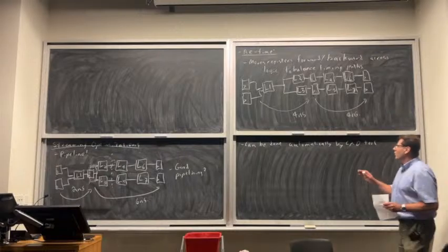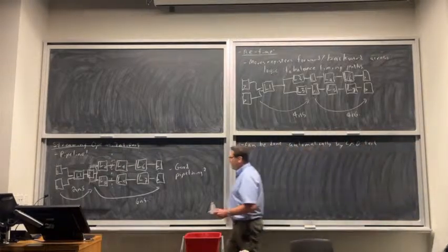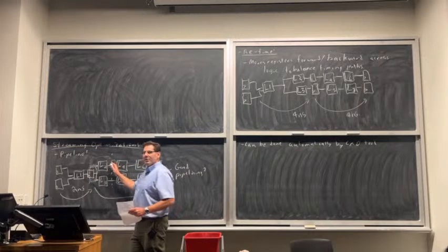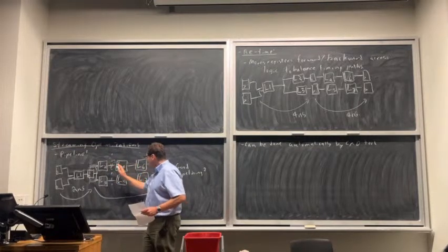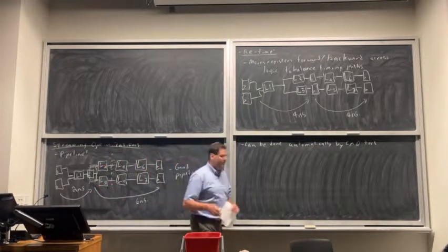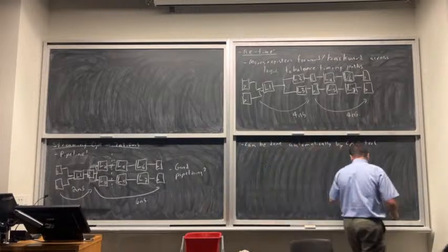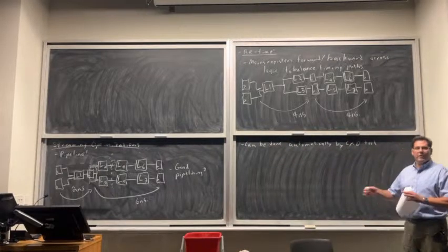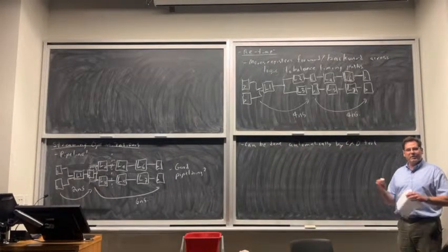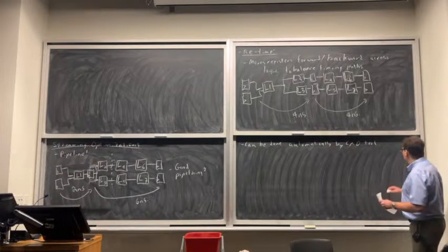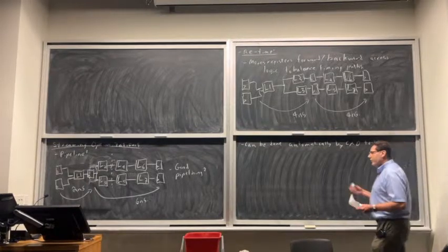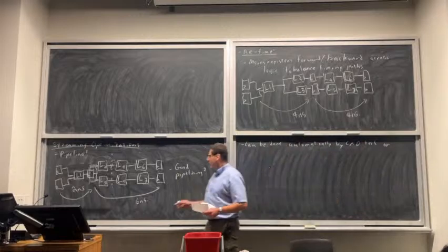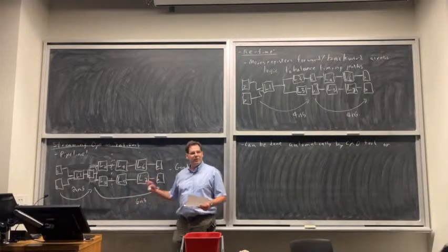But you can do it locally. If I move this register, I need to make 2 copies, right? If I move registers backwards, I need to make sure there's a copy on every one of the outputs. So you can use that to rewrite your HDL if you're finding that your timing paths are unbalanced. Although you don't have as fine-grained control. In your HDL, you don't quite know where the lookup tables are. You sort of have to guess.